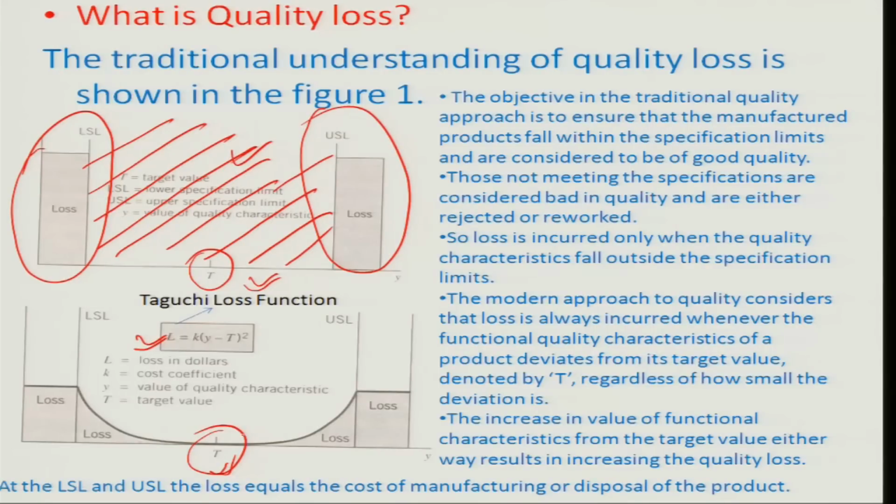So, here for example, if I was talking about a shaft diameter having a value of 1 plus minus 0.03, meaning thereby the design spec says that the shaft can go between 0.97 to 1.03.